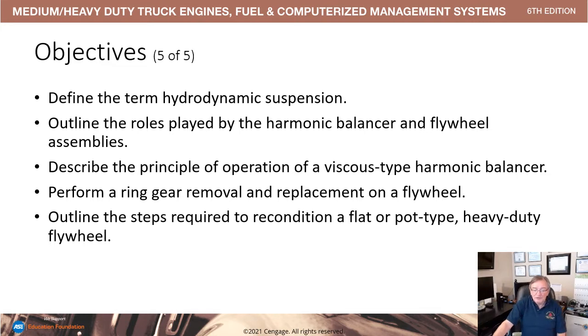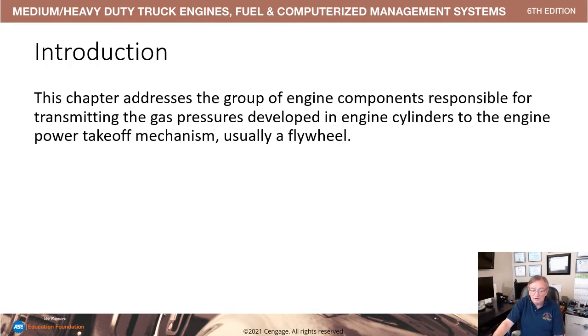Define the term hydrodynamic suspension, outline the role of harmonic balancer and flywheel assemblies, and the principles of operation of a viscous type harmonic balancer. You're going to be doing piston removal and replacement, and for the flywheel, you will outline the steps to recondition a flat or pot type heavy-duty flywheel.